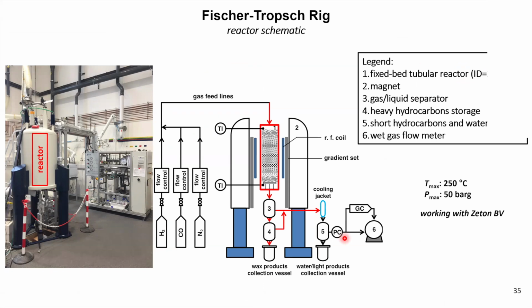And here's a schematic and an image of the reactor setup. On the right-hand side, we've got our flow control and the flow coming across the beam here, and then we've got our reactor inside the magnet. This reactor has to be suitable for looking at operando conditions, real industrially relevant conditions. So it is designed to operate at up to 250 degrees centigrade and 50 atmospheres pressure.